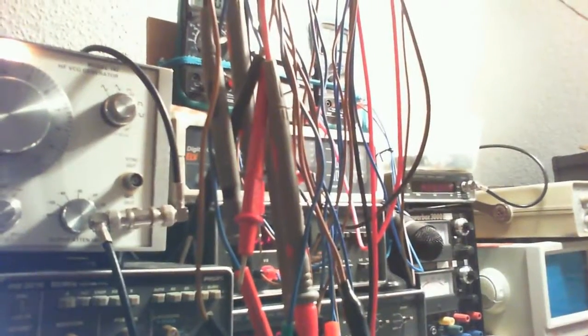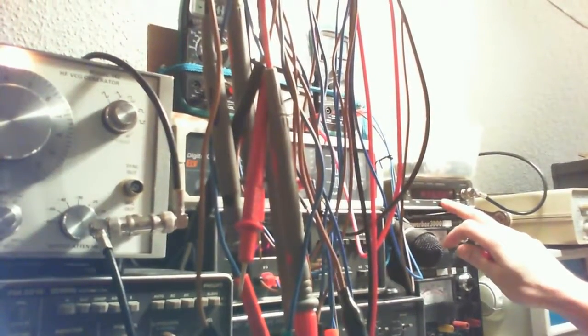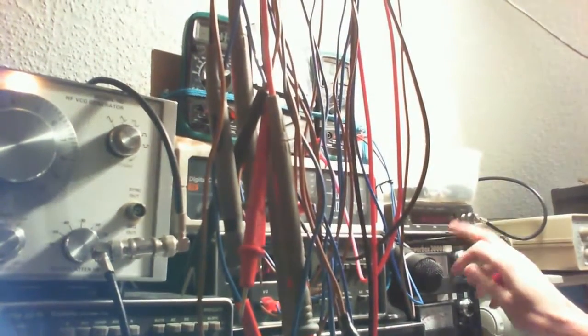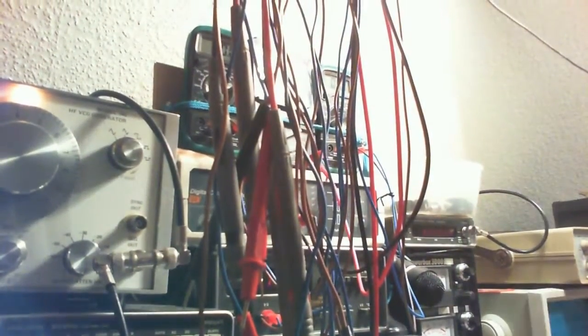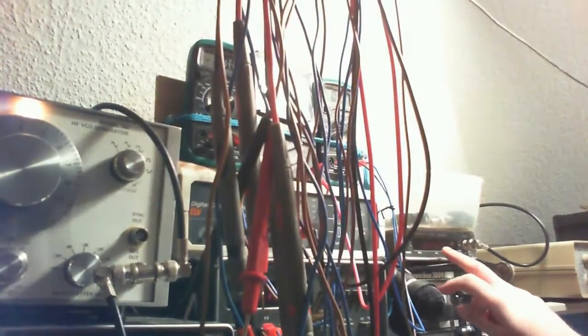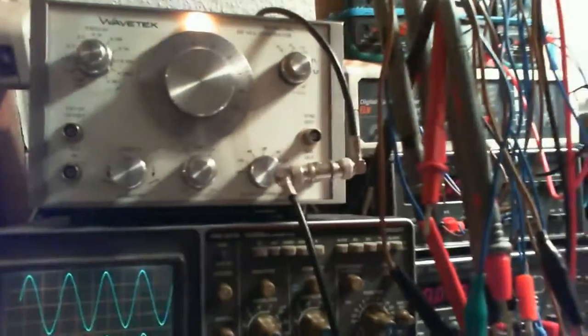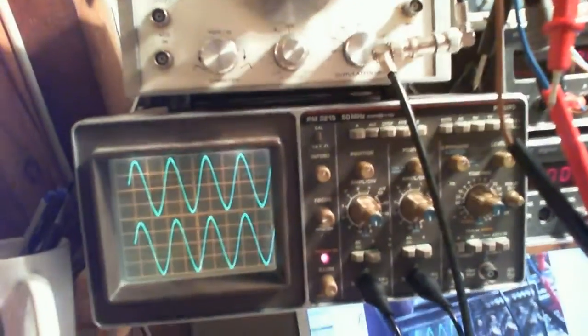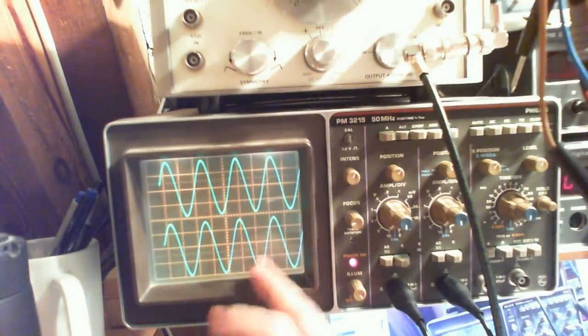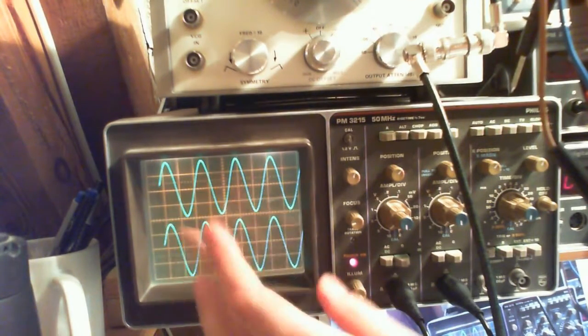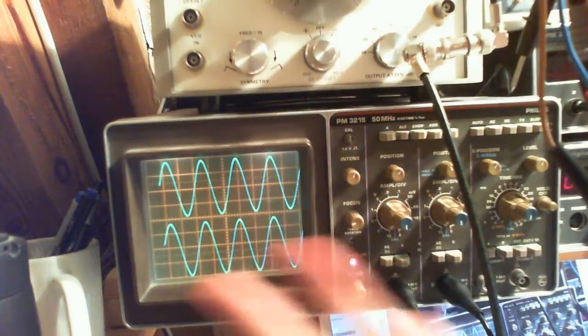And if you read up here on the frequency counter, you have 426.967 kilohertz, right? So 426.9, 427, versus this 421. Of course, it's not always easy to read everything very accurately on an oscilloscope, but it gives you some clue as to what sort of frequency you have on your wave.